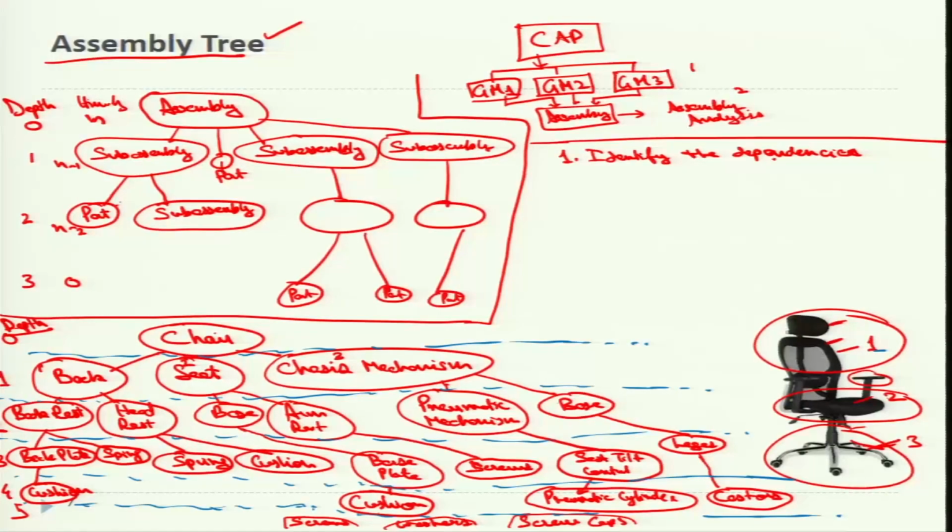So, identify the dependencies, I would better say interdependencies as well. The best approach to create this assembly is to create the two blocks as separate parts and merge them into a blank assembly model. This is known as the bottom up approach, making the small components, making sub-assemblies out of them, then trying to make a full model out of it.